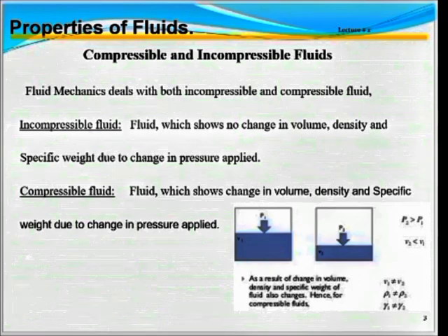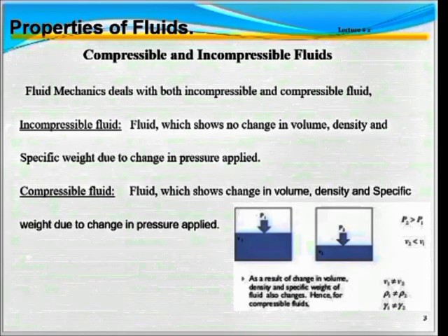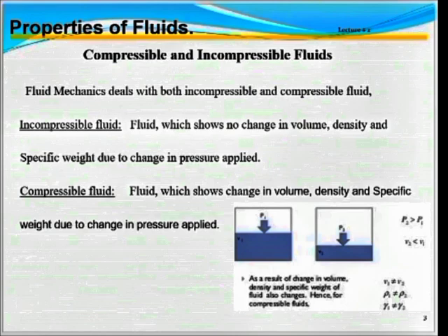which is the centimeter-gram-second system. So an incompressible fluid is actually that fluid which shows no change in volume, density and specific weight due to change in pressure applied, while a compressible fluid is that fluid which shows change in volume, density and specific weight due to change in pressure applied.